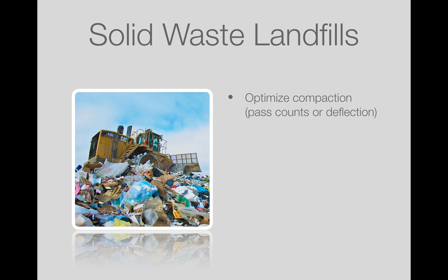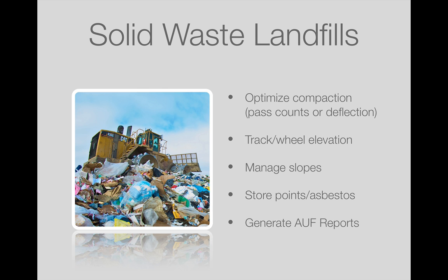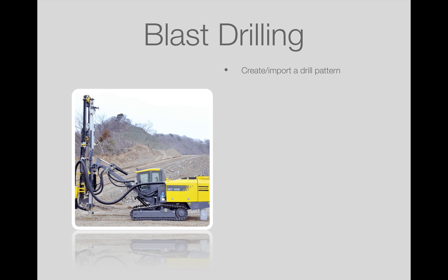Solid waste landfills, for example, are primarily track elevation. They're compacting the waste stream, building slopes. So track elevation is all they need. So we can apply the particular application software that will monitor pass counts, that will allow the operator to manage the slopes. They may need to store points for hazardous material. And of course, there are certain application-centric reports that need to be generated. But again, the solid waste landfill has its own application requirements, and we're able to use the components, create a machine control system for that, have certain user interface features that apply to that application, and then very easily provide a nice solution.